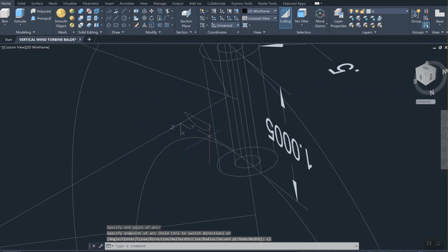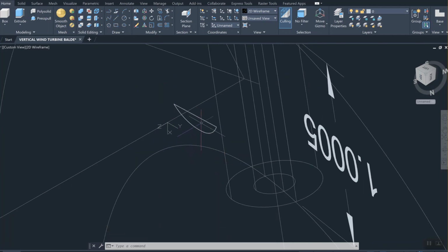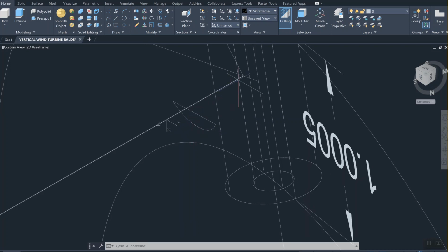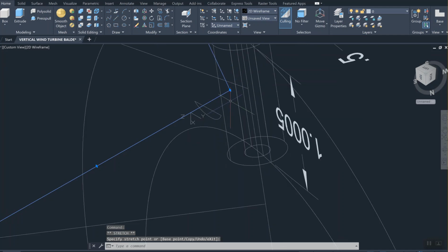So this particular design is called an airfoil, and I'm going to use this one and just copy it to make two copies. In the meantime, I'd like to relocate this profile a little bit halfway in, because we don't want this extrusion to reach the center.